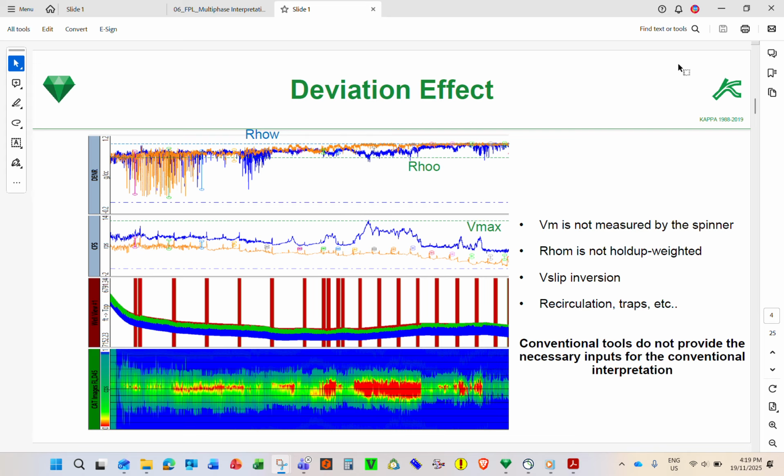So that's why you cannot use the conventional spinner. You can see it's moving up, it's 90 degrees, it's more than 90 degrees, it's moving down. So probably when you are on the down pass, your spinner CFS is reading on the water going downhill, which is faster. So this is going downhill faster, and then you start again at 90 degrees, it's flat.